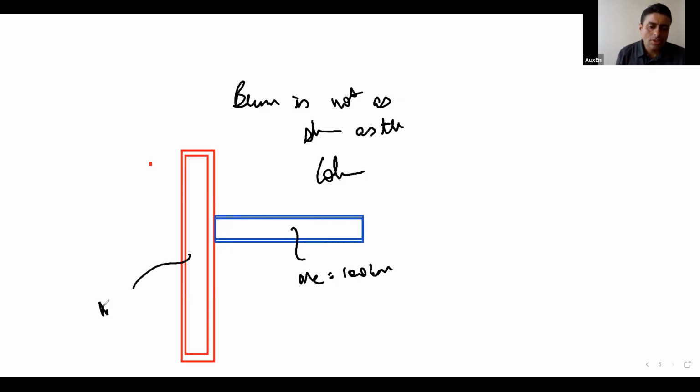The moment capacity of this column is, let's say, 160 kilonewton meter. So have you achieved the strong column, weak beam theory over here? You have achieved it in practical terms, the strong column, weak beam concept. But you can still make this a rigid connection. What is the harm? Are you getting this?